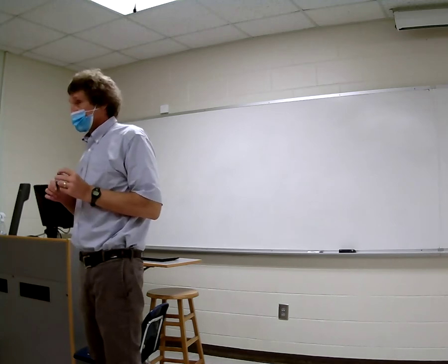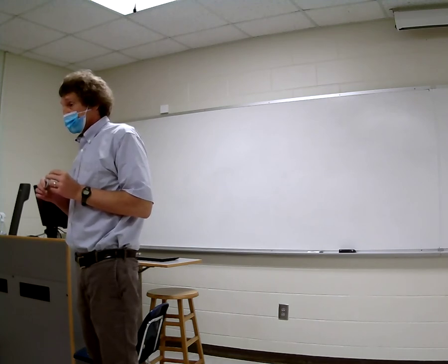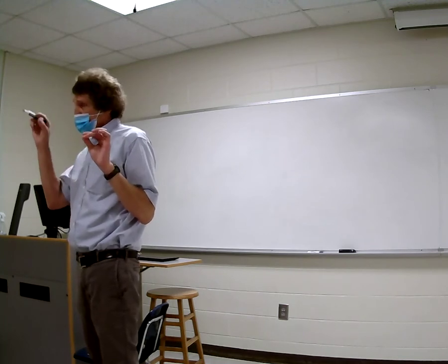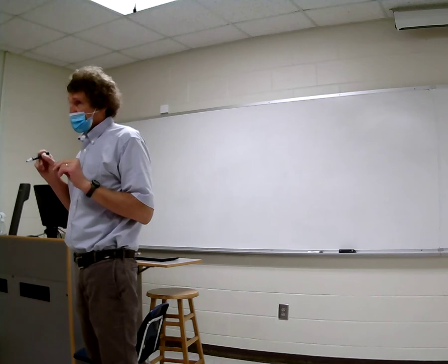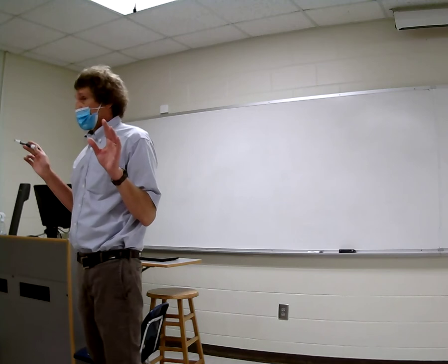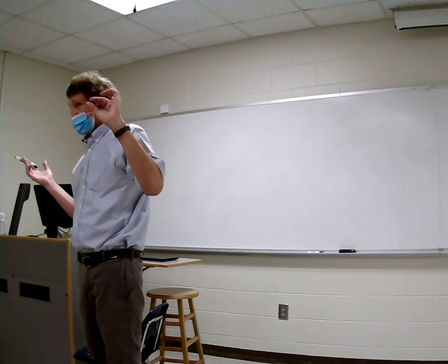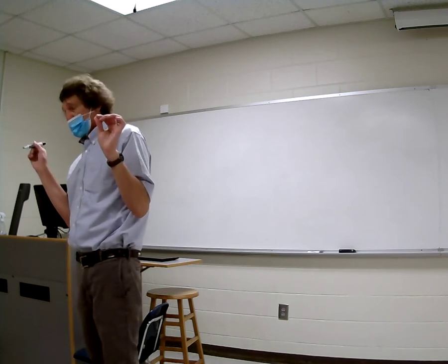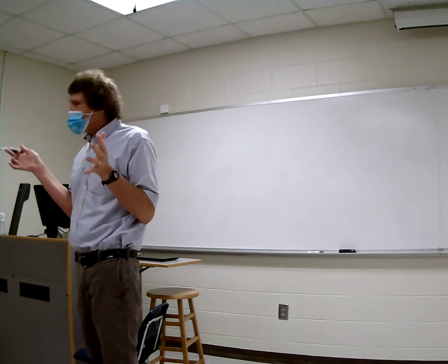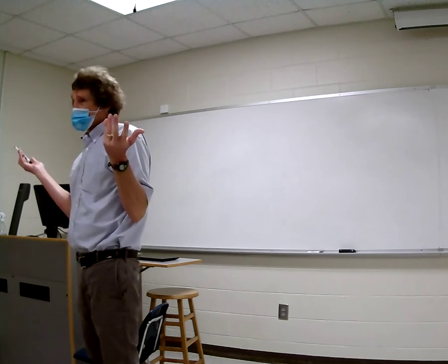Go ahead, Jay. I just had a quick conceptual question. You know how skin depth becomes a big problem with normal transmission lines? Well, skin depth isn't a problem with transmission lines. Skin depth is the current hugging the surface of the conductor. Doesn't that increase resistance quite a bit? It can, but copper's resistivity is extremely low, I mean its conductivity is very high. Even with a small skin depth, remember we were calculating AC resistances? At gigahertz frequencies, the line losses are trivial. It might be a half ohm, a quarter ohm, but your characteristic impedance is 50 ohms, so you don't worry about that. But we'll go through it.